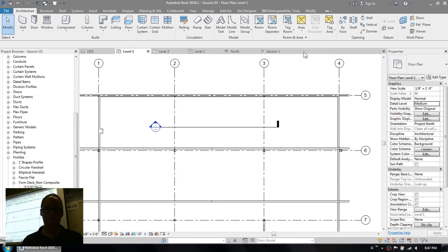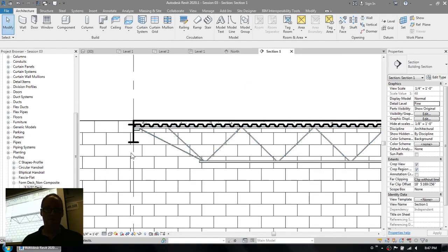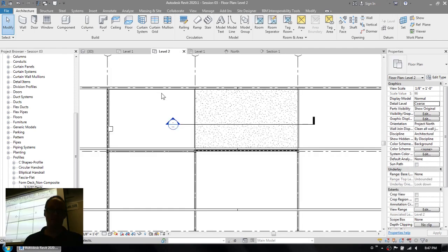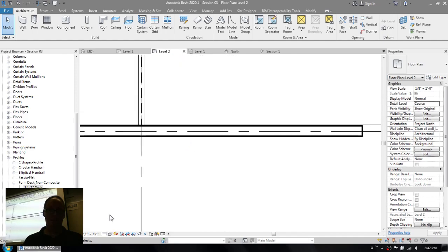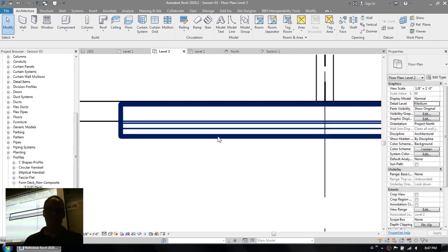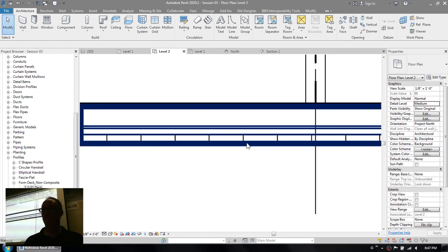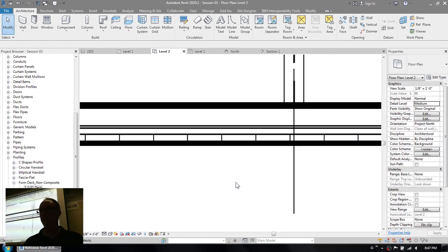Well, what's going on is that Revit is doing these things in 2D in this view. It's not 3D. Another thing that is not 3D, I don't know if you guys have ever thought about this, but you know all these different material lines that you see in the wall here? Fake news. They don't exist. What you're seeing here are 2D lines, 2D hatching that the software puts in to show where all those different material layers are in the wall.